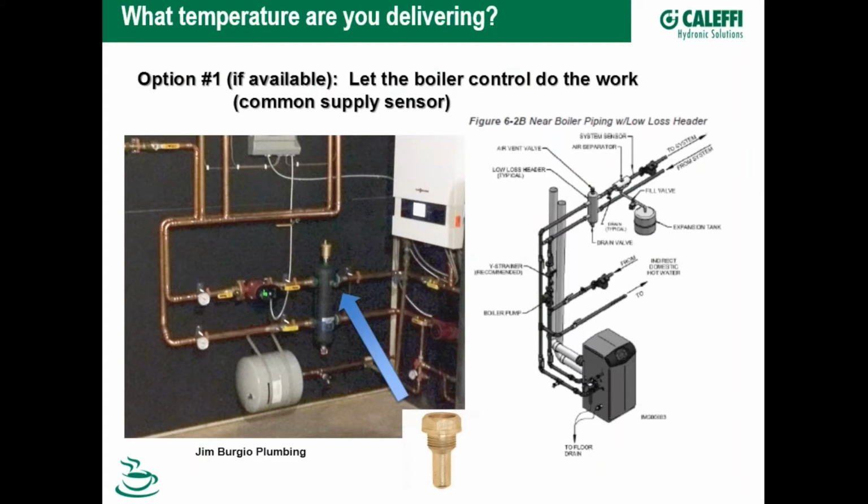Yeah, there are some boilers out there that will offer the option of doing what's called a supply sensor, or a common supply sensor. If you look at the Lochinvar diagram off to the right-hand side, you'll see it up here listed as a system sensor. And if you notice looking at the plug here on the front of the hydro separator, it doesn't have that shiny brass look because somebody has converted it over with the well to put the supply sensor in there. What happens with this sensor is by putting that sensor in and feeding it back to the boiler, that now can become the control point.